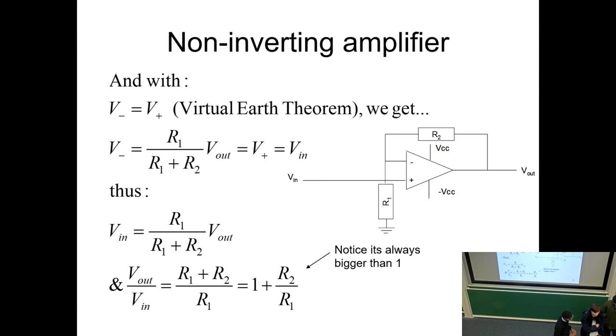And it can only do it if the gain of this is very, very high. And the gain of this falls away with frequency. So when you get to a megahertz, for example, for a 741 op amp, it's all over, and it's not really an op amp anymore. Okay, all right. So A is then 1 rather than 100,000. And if you put 1 into those equations, you'll get the right answer, but it won't be very high.